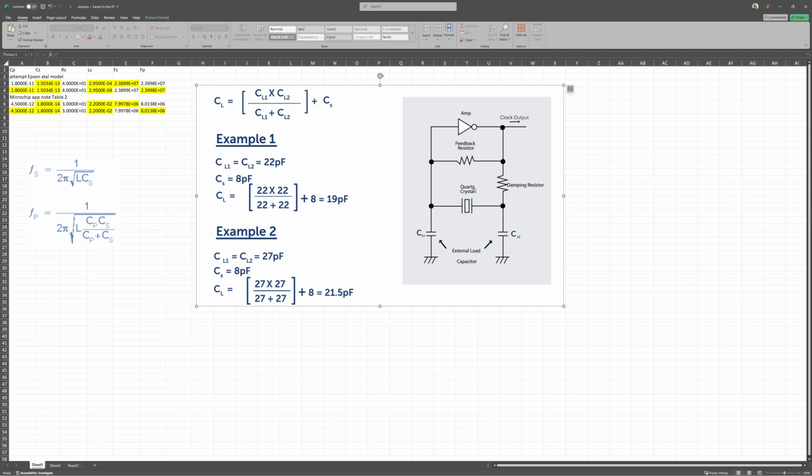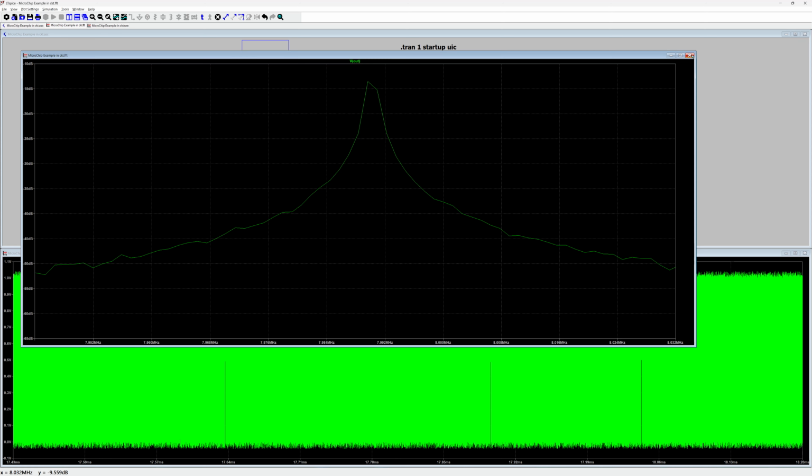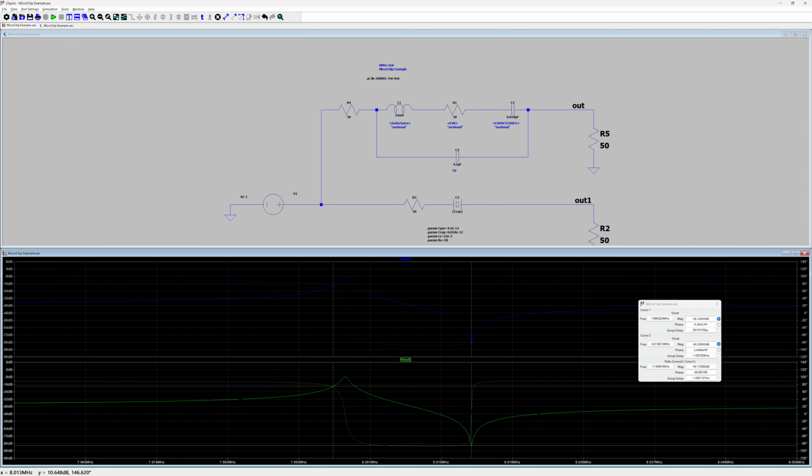And you can plug those things into a SPICE model and get it part of a transient analysis, and you can put the model into an AC analysis and get your Bode plots. The help file recommends that you use their composite symbol instead of individual components, as this simulates faster.